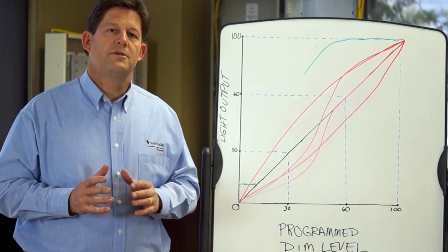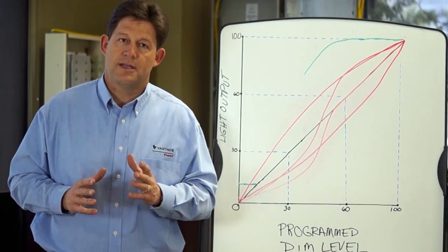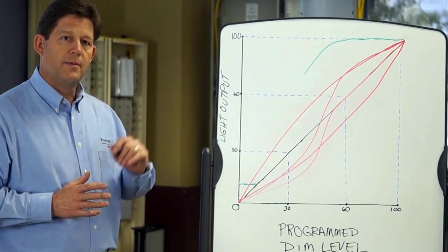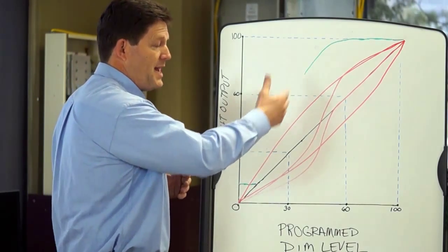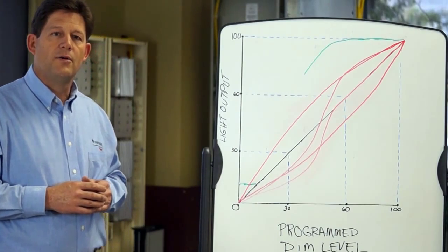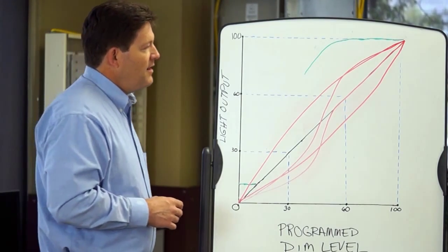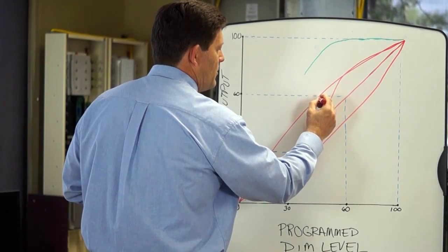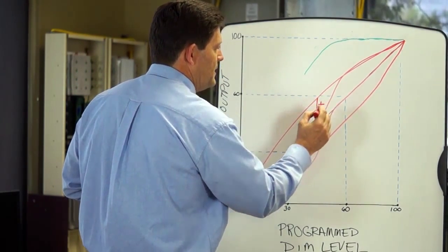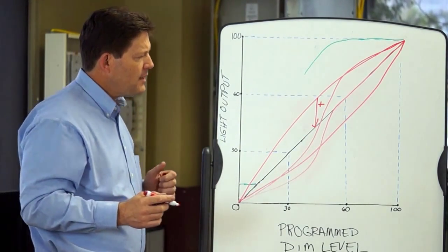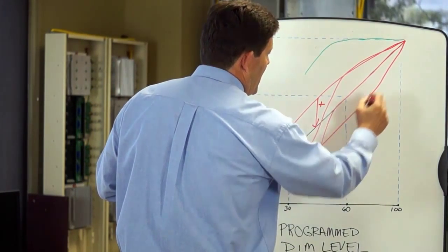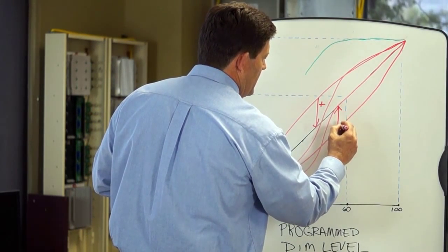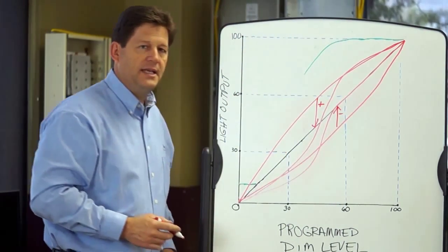The analogy we often use to explain the impact of the adjust parameter is that of a rubber band. With the two ends of the rubber band fixed by the minimum on and the maximum on parameters, there are obviously many paths that the rubber band could follow between the two points. If the rubber band is bowing up, what we want to do is drive each point down, and we would do that by increasing the adjust factor. If conversely the pathway is bowing downward, we want to drive each point upward, and that is done by decreasing the adjust factor.